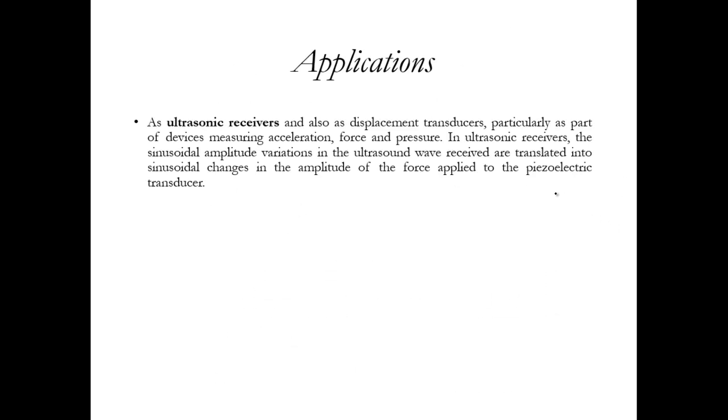The applications are considerable. We have ultrasonic receivers, which are also called displacement transducers. They are devices for measuring acceleration, force, and pressure. The piezoelectric materials can be used as ultrasonic receivers because they can take the vibrations in the form of ultrasonic waves, and that can be converted to voltage at the ends of the piezoelectric material.